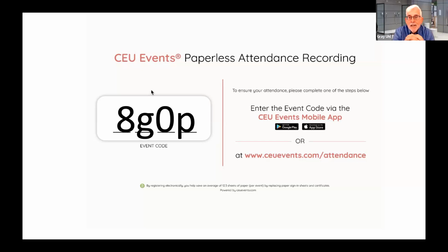Now, having said that, you do reach a point where, to get a satisfying shower, you go below a level where it's just really hard, even with the latest technology. So where we've landed here in the US at the moment, there are a number of states in the United States that are down to 1.75 gallons per minute flow rate. And we're still able to engineer. You've got to look for well-constructed and engineered product, but we can engineer a shower head or a handheld shower that delivers a really nice, satisfying performance.